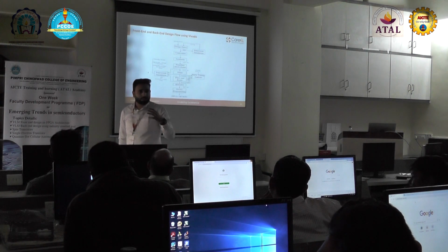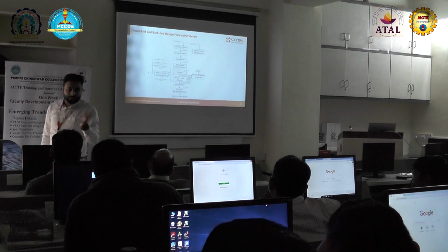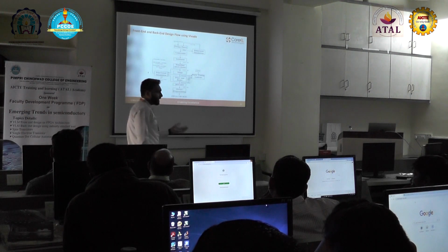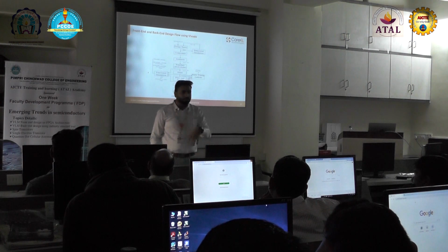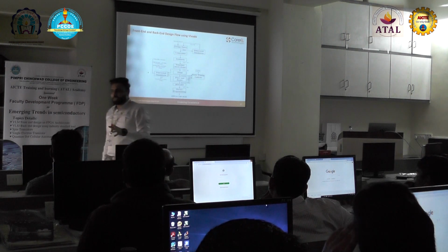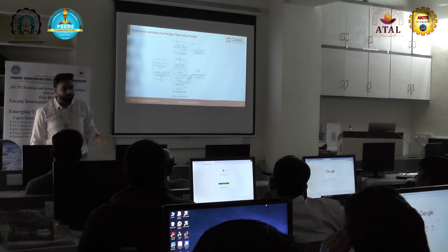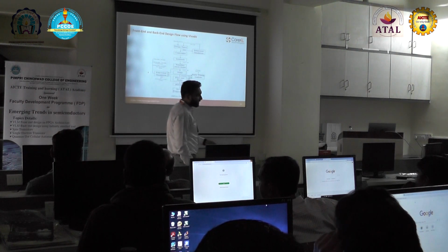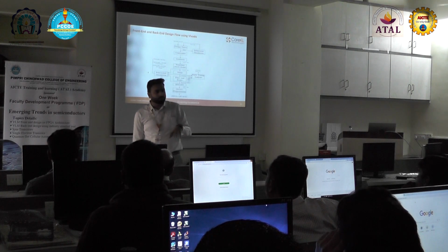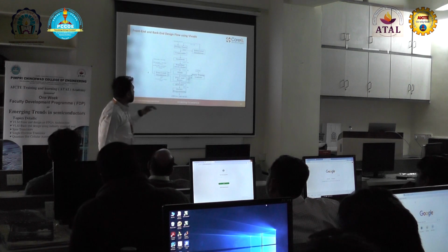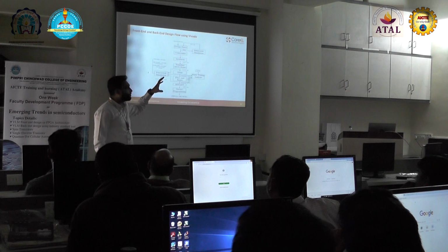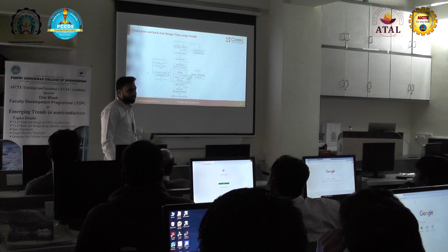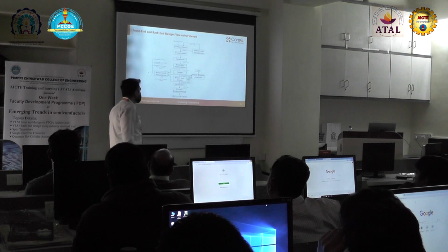If you are using Basys 3, the Basys 3 master XDC; if you are using Nexys A7, the Nexys A7 master XDC file. These files contain all the inputs, outputs, clocks, push buttons, counters, seven segments, all the information of the board, in the constraint file that you are going to access, and you give the constraints in the XDC file, right?